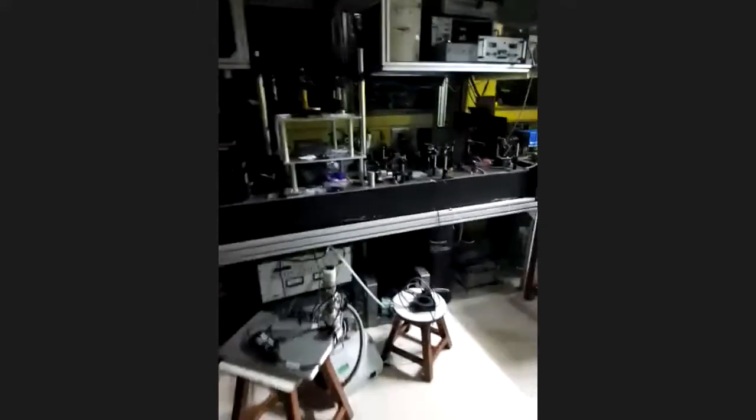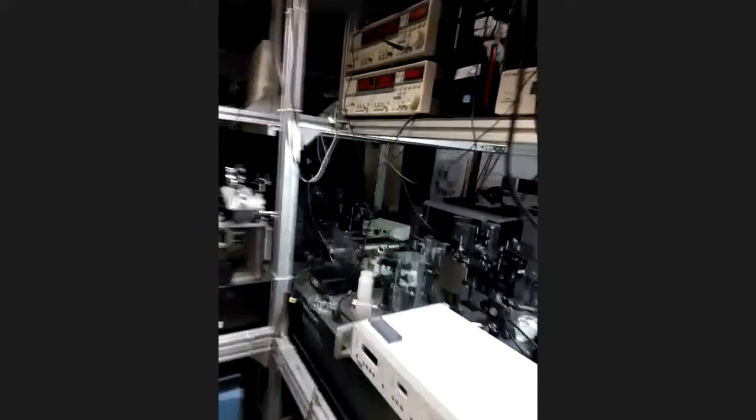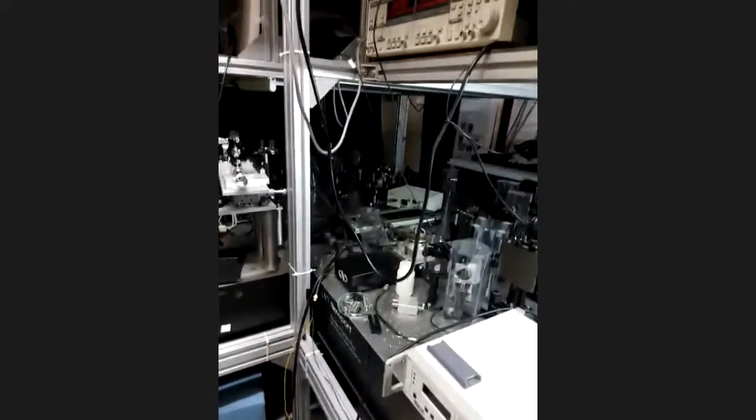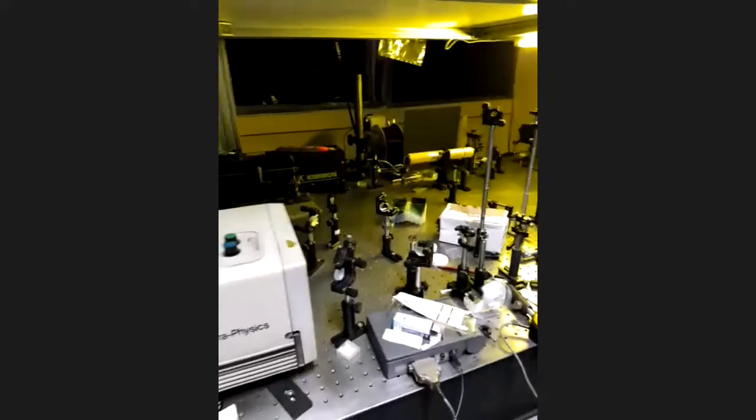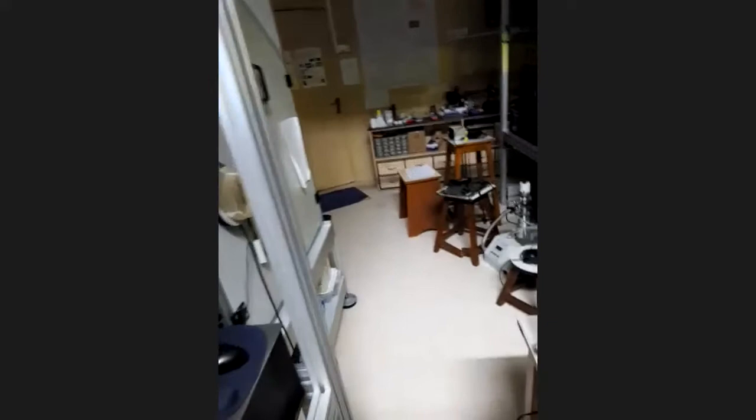Okay? So then to further improve the noise, I said we do the lock-in detection. Right? So that we modulate the input light and then we measure the signal coming only at the particular frequency where we are modulating the input light. Okay. So sources of noise will be from noise in the light source, right? So that we can't do much about, but the external noises are what we take care of.